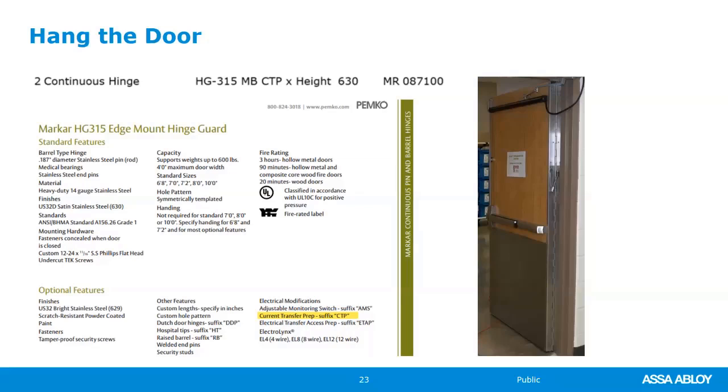One of the questions is, would you go to the architect and recommend a hollow metal door versus a wood door? In certain cases, yes, I would, absolutely. If, for example, they said, we want concealed vertical rods, then I would highly recommend to the architect that they change those doors to hollow metal. If it's a hollow metal door that needs to look like wood, Curries and Seco make the Madera doors with the wood grain. So you can make a metal door look like a wood door if they need the look of wood, but the durability of hollow metal.